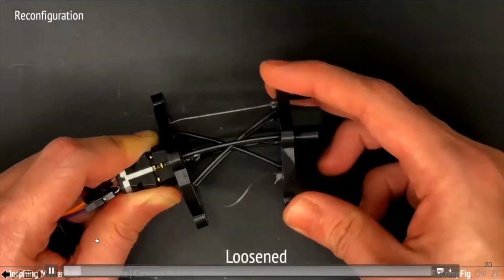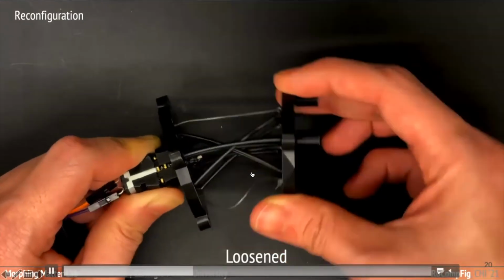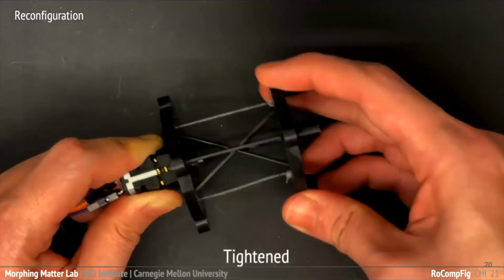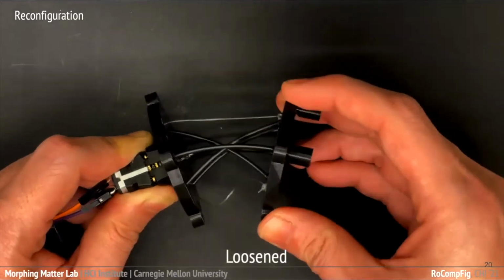And in our case, we're using the motor to reconfigure the tightness of the cables. So when the cables are loose, the structure is actually free to move around however you want. But when you tighten the cables, they become a constraining element that prevents the structure from moving.